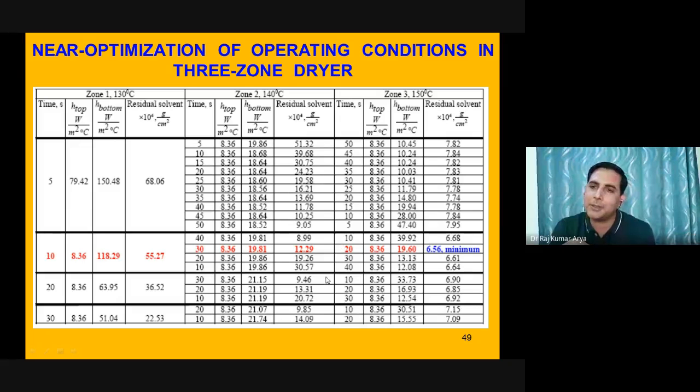Here the same thing happens in the case of coating also, because in polymers, when the concentration of polymer becomes 70%, the diffusion rate decreases extremely low, 10 to the power minus 13. So for that, your drying on top should also be in that order of magnitude, it must also be decreased. Otherwise, you are providing heat to the polymer, but solvent is not present. So it will burn your polymer or film.